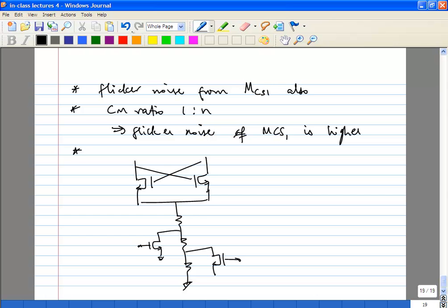Of course, you don't have any 1/f noise. Obviously, you only have resistors now. Now your first problem is you have bias current variation over PVT. Your bias current is no longer constant. It depends on the VGS and the resistor values. Resistor values will change with temperature and process, and the same thing with your transistors. PVT variations will change the VGS.